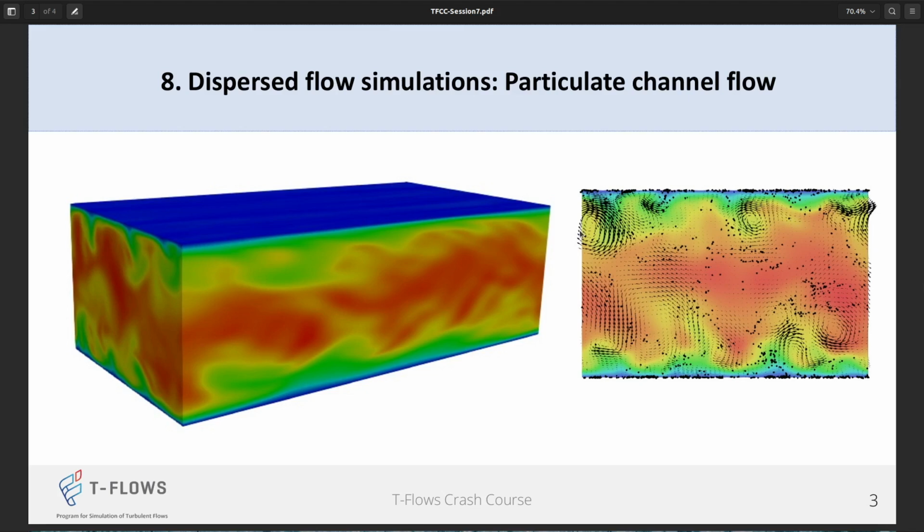What I'm going to show you today is just to develop the flow until it reaches a turbulent state, and we can see these turbulent eddies inside the domain. And once we have that state, we don't wait until the flow is fully developed, but you can definitely feel free to do so on your side. It's just that for the sake of relevance and also the time limit, I'm gonna show you how to develop the flow into this turbulent state. And then once you have a turbulent state, you can impose particles.